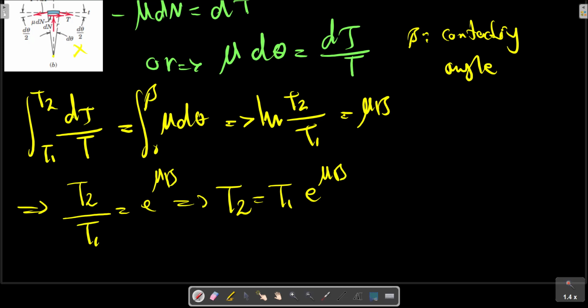The relation also applies to belt drives where both the belt and the pulley are rotating at a constant speed. In this case, the equation describes the ratio of belt tensions for slippage or impending slippage. When the speed of rotation becomes large, the belt tends to leave the rim, so equation 6.7 involves some error in this case.